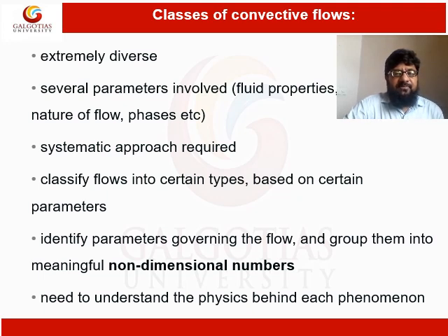There are several parameters involved, like the fluid properties, geometry, nature of flow, phase, etc. We must identify each of these: whether the flow is natural or forced, and what the phase of the fluid is when it comes into contact with the heated solid surface. What is the nature of flow, whether it is turbulent or laminar. All of this information is required whenever we want to solve a convective flow problem.